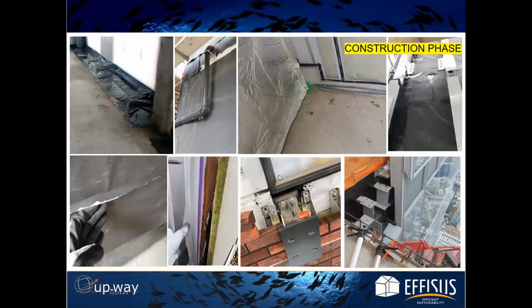Here, for instance, you can also see some water accumulation or water that is stagnated, which will lead to system failure. Wrong perforation sealing, because most of the times teams at site don't know exactly how to deal with these kind of perforations. Lack of sealing in some areas that you can find as well. Use of incorrect accessories, which is very common.